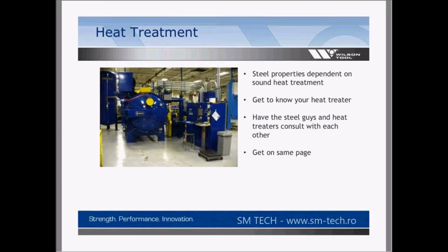heat treatment of material makes a big difference, only in the fact that it provides you that hardness and toughness of that product. Any changes in your heat treatment can take away anything you've done in your tool steel changes. You might be running M2 and you went to a 10V, but it was not drawn properly. Next thing you know, you're getting less wear resistance, and you're seeing problems all over the place. You're getting chipping, and you think it's because it's too soft. You make it harder, but it's just a draw temperature issue, or it didn't dwell long enough at temp in the vacuum furnace, or the quench time was too slow or too quick.